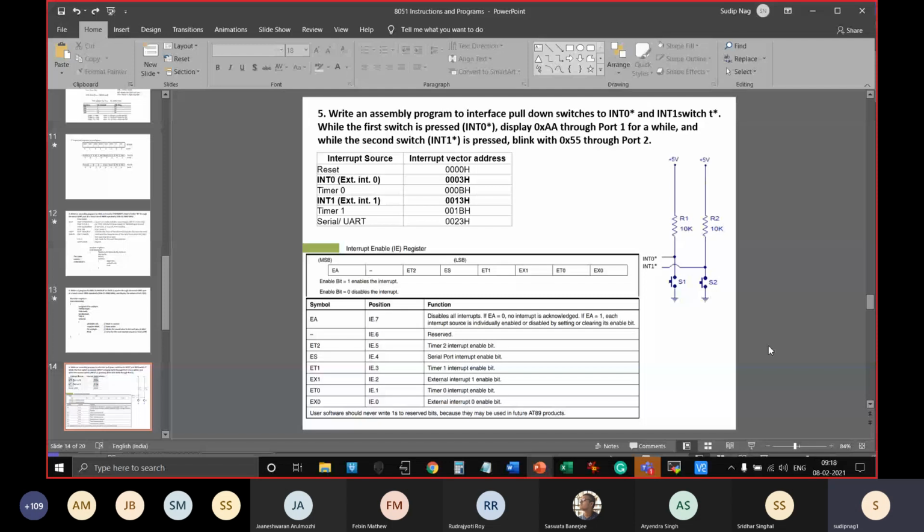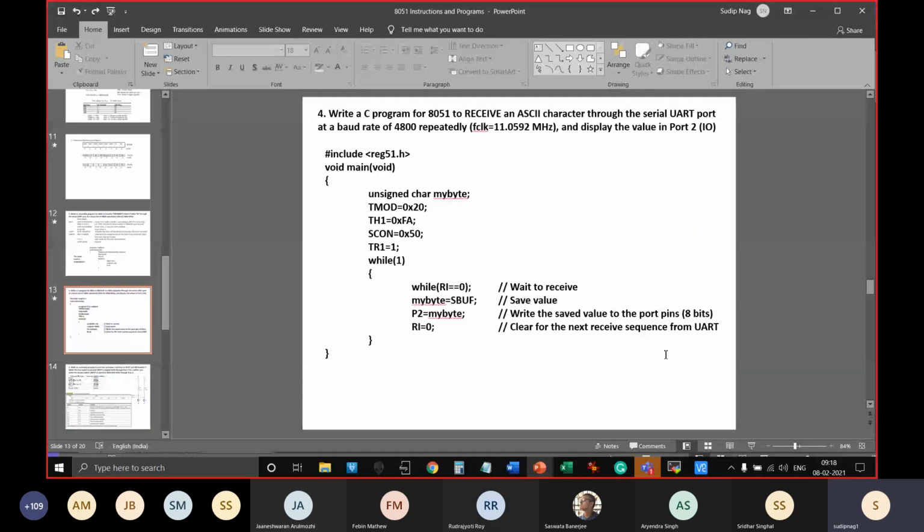The code also looks pretty much similar, only the names of the registers will change in ARM, or the way that we access the bits and bytes will change. So instead of character variables, we'll be using integer variables for 32-bit or 16-bit numbers. Those things are going to change in ARM-like processors.